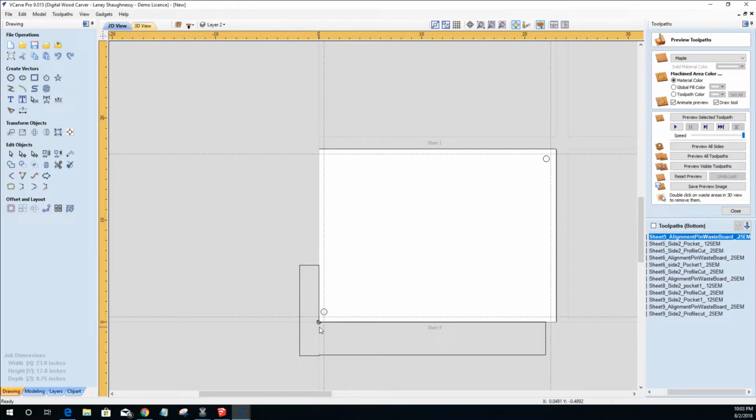Yeah, William, you're exactly right. You got to hit yourself just a little bit. Good way of thinking, but it was two separate things. The DWC Quickset is great for finding X, Y, 0 and Z 0 on your board, your corner, but that's different than using the jig to help with placement on the table, where our boards are always landing in the same exact spot, so that when we flip it over, we're always landing on the same exact alignment pin holes if we only cut our alignment pin holes once.